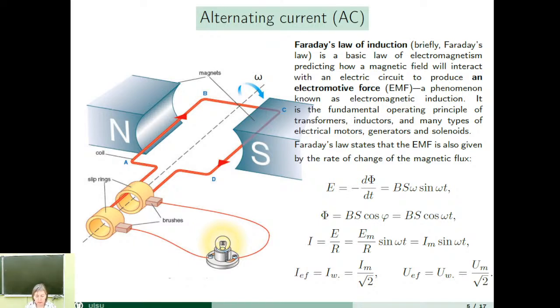When it is stated that the alternating current potential difference between the supply means is 220 volts, this means the effective potential difference is 220 volts, and the peak value is 311 volts.